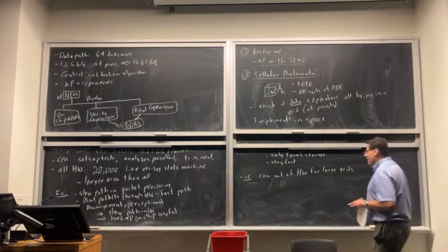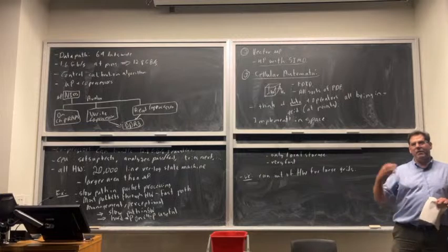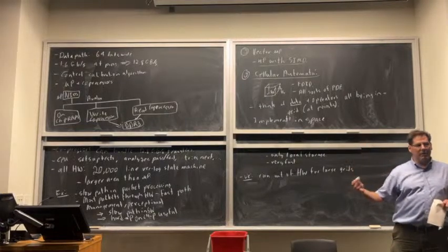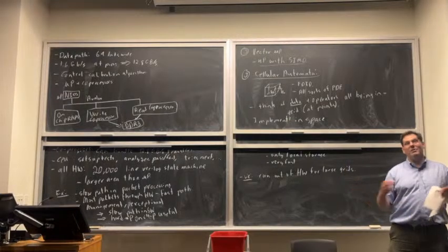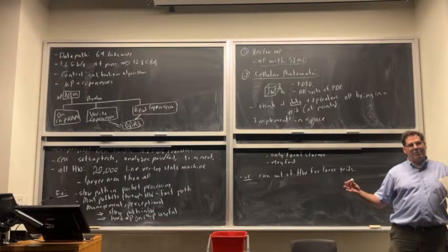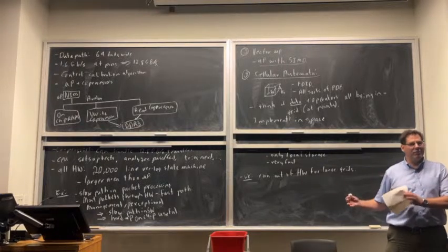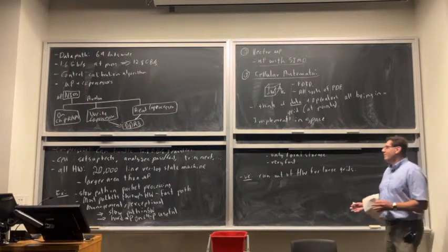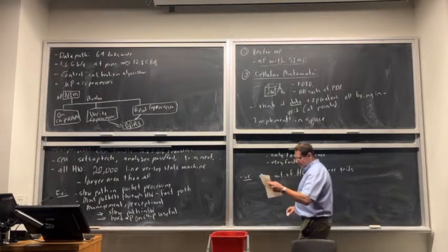But it needed a million-LE FPGA in order to solve, in hardware, the placement for a 2000-LE FPGA. So it was really fast, but he needed a really big FPGA that he'd actually placed and routed in order to solve the placement problem really fast for a small FPGA. So that's the problem with this. The biggest problems are what we care the most about.